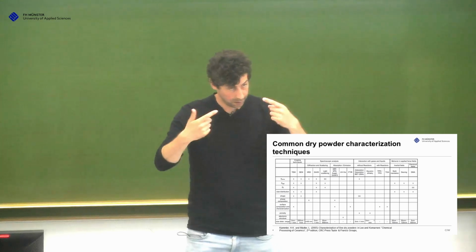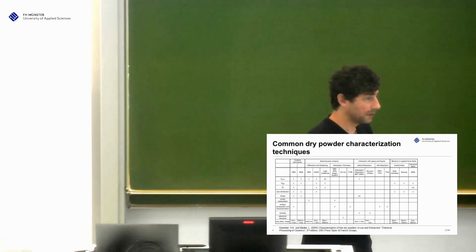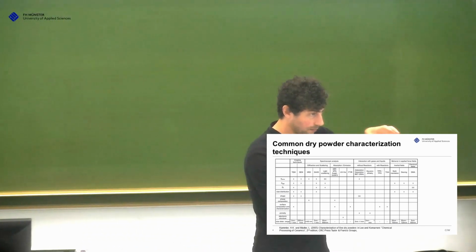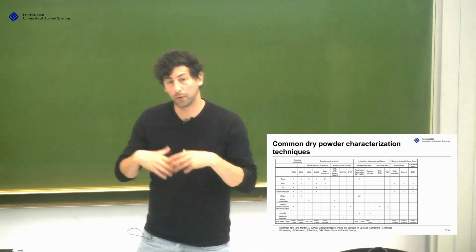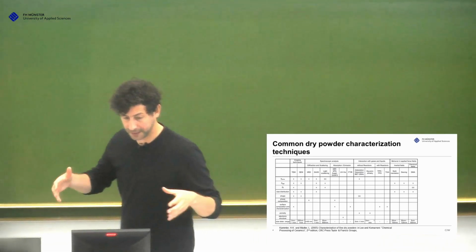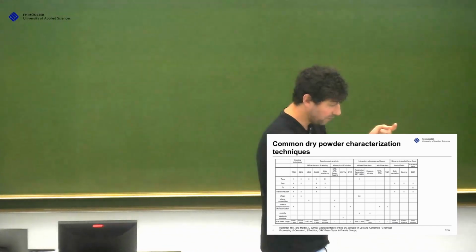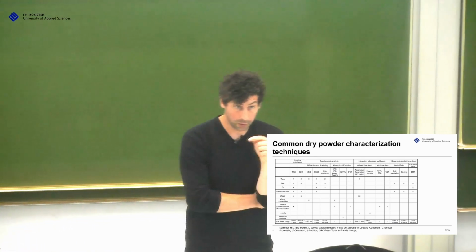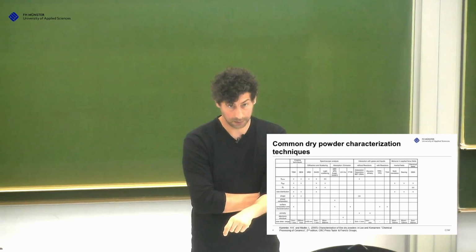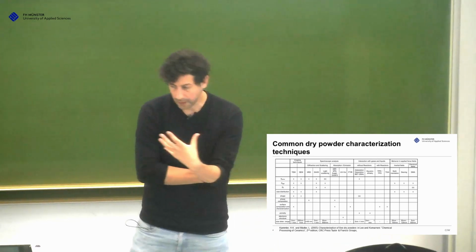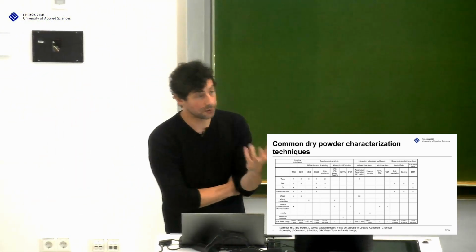And then nitrogen goes in. You're pumping nitrogen at different pressures. And the nitrogen will go, for different pressures, to the surface or not. And from there, you can determine basically the porosity and the specific surface area, because you know how the nitrogen behaves, and you can just count how much goes in and how much goes out, and the difference will stay on the surface of the powder. With this, you can determine in a very simple experiment porosities and specific surface areas.